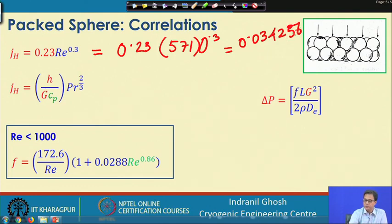So, this will come out to be 0.034256. This would be the value of the Colburn J factor, and the Colburn J factor is nothing but the Stanton number times Prandtl number to the power 2/3. The Stanton number is h by G Cp. We already have an idea about the G, which we obtained. We also know from the fluid properties of nitrogen the value of Cp. So, we can calculate the heat transfer coefficient, which is what we are looking for, from this relation.